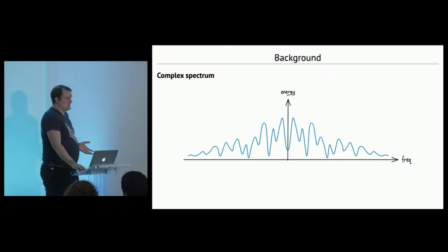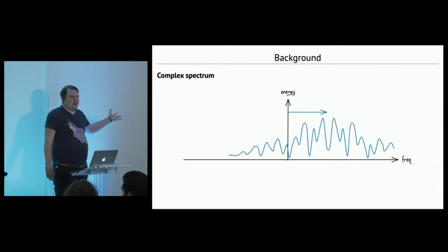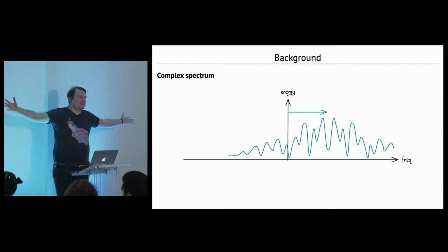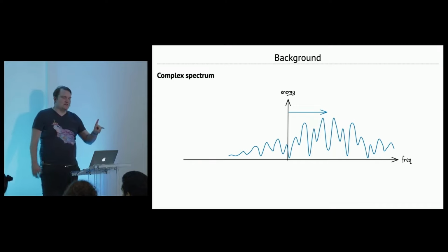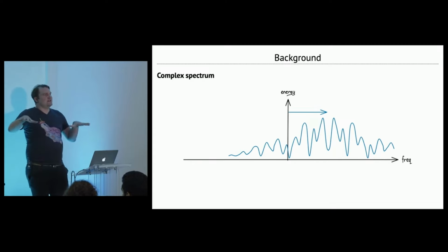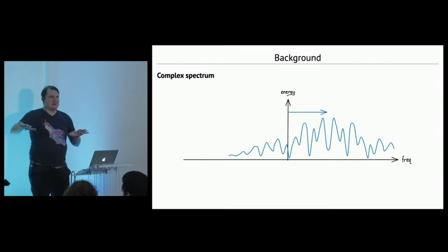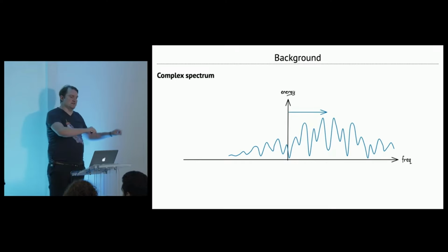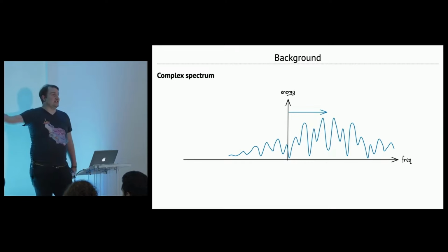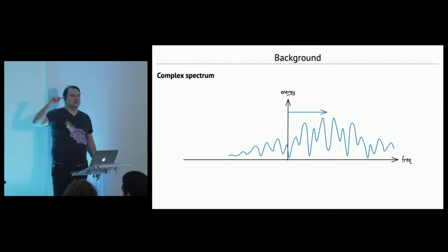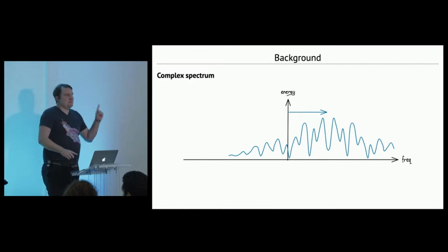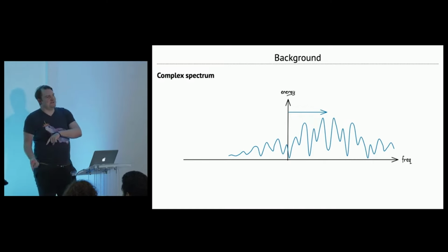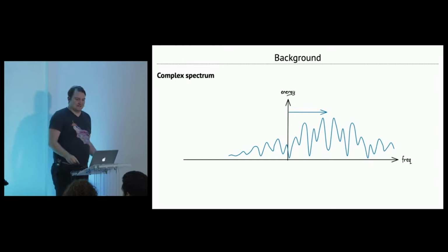And there are some things you might want to do. This is a really common thing to want to do, is frequency shifting, where, unlike pitch shifting, which is a different talk, you shift everything in the signal by a fixed number of hertz, up or down. And this is actually really easy to do, right? You just modulate your signal with a complex exponential. It's very straightforward. The problem comes is that you need to convert it back to real afterwards.